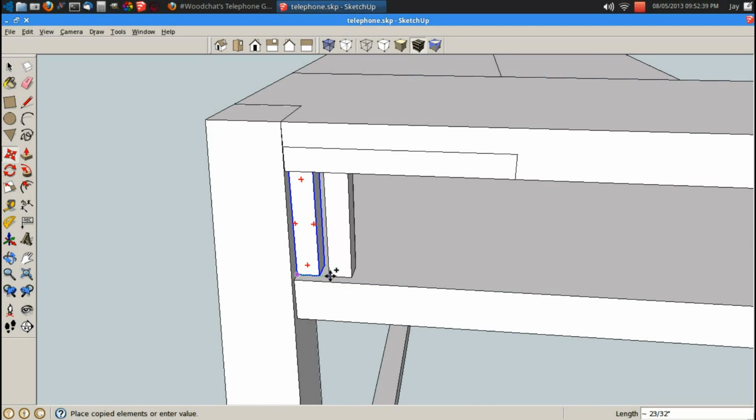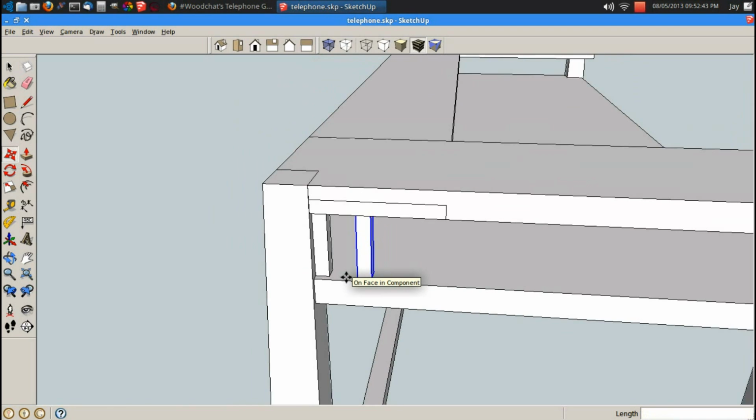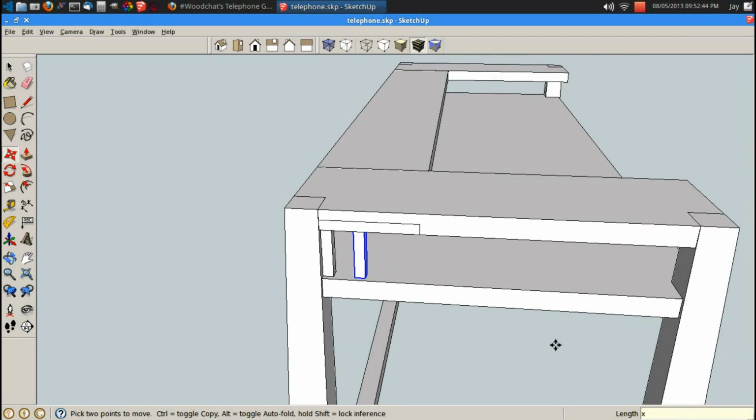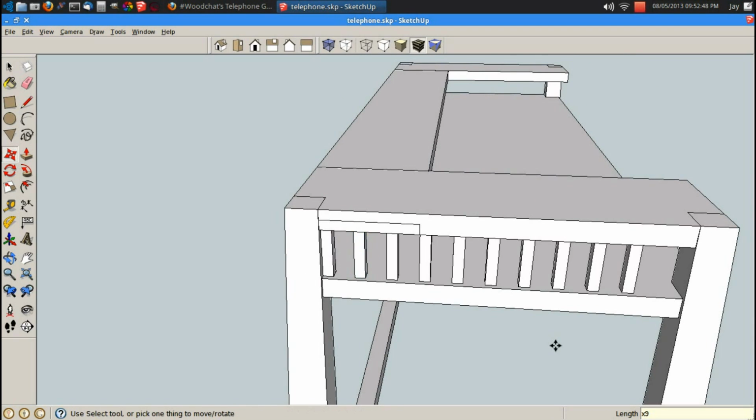They're a half inch wide, and I want a 1 inch spacing, so let's move it 1.5 inches along the green axis, and let's duplicate that by say 9. So X9, enter. That's not enough. X10, enter. That's the good number.